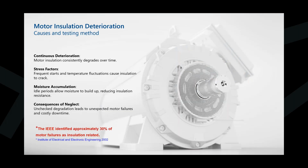So to start off, we know that motors over time consistently degrade with respect to their insulation. And in addition to that, frequent starts and temperature fluctuations can cause insulation to crack. Also, idle periods allow moisture to build up when the motor is not in use, reducing insulation resistance. So unchecked degradation leads to unexpected motor failures and costly downtime for when you need that motor to be running for your processes. The IEEE identifies approximately 30% of motor failures are insulation related.